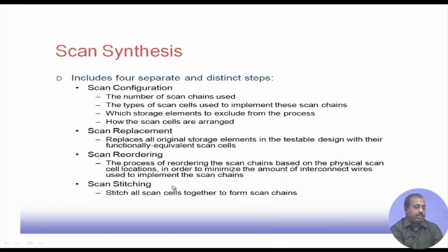And finally scan stitching. We have to stitch all the scan cells together to form scan chains. So the output of one scan cell should go to the input of another scan cell, like that. Those connections are to be established. So that is actually the scan stitching.